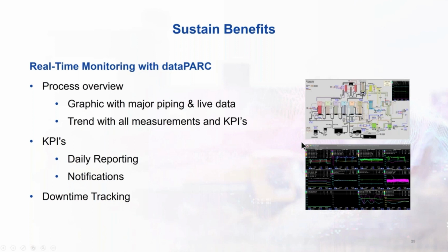And we tend to have a screen of trends. Sometimes it takes 2 screens of trends, but if we can get it all on one, and for most unit operations we can, all the key things, then in one place you can see if you're having a problem. You see all the tags. Otherwise, the tendency is let's grab a tag here, grab a tag there, add a 3rd tag, add a 4th tag. That works, okay, but you sometimes miss something else that's going on, where if you look at all the trends at the same time, you notice, down in the corner, how come this is oscillating? Or hey, every time we go down, something happens in another part of the display.